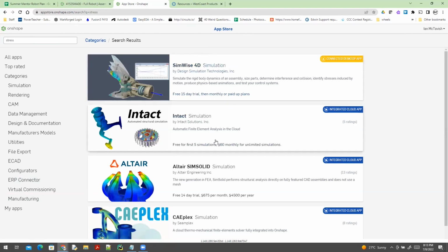But there are some free ones, and it's being strategic about it. If you've got multiple CAD members, then using these later on really helps. The other thing is that there's certain strategies that help. So if you're going to be 3D printing, really look at your infill percentage. There's certain things you can do to make the part that much more durable.